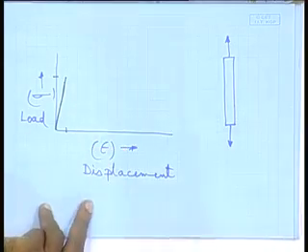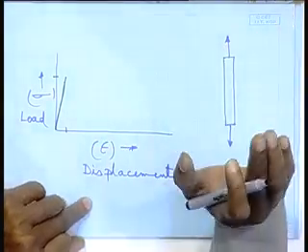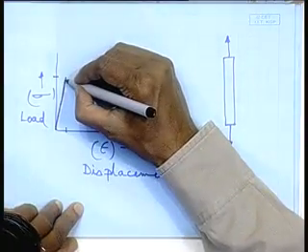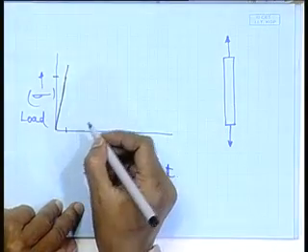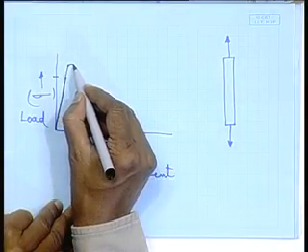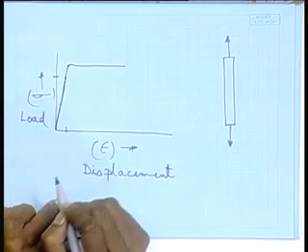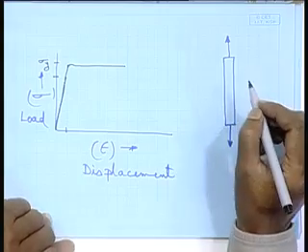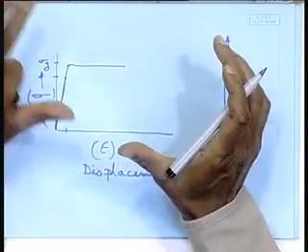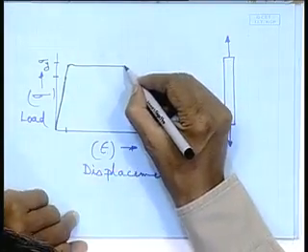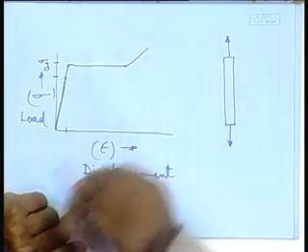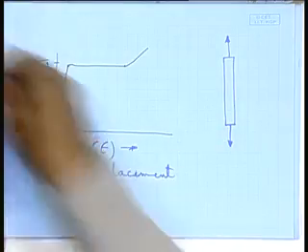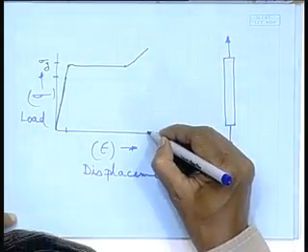But in our plate bending, I will have to have a remaining deflection. That means a permanent set, as we call it. Permanent deformation is needed. That means I will have to exceed the yield point. Say my yield point is here. And then what happens? It goes somewhat like this. This is my yield point. I need further displacement or more deformation, then the work hardening starts like this, and I stop there. Why do I stop there? Because the strain needed is, say, this much.